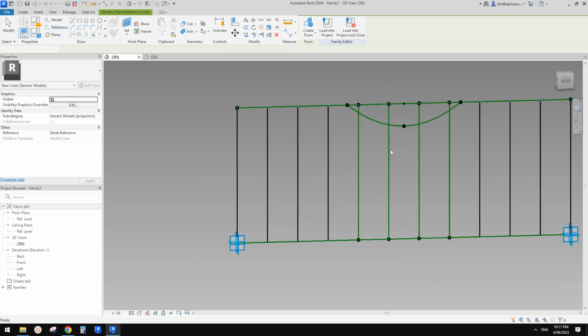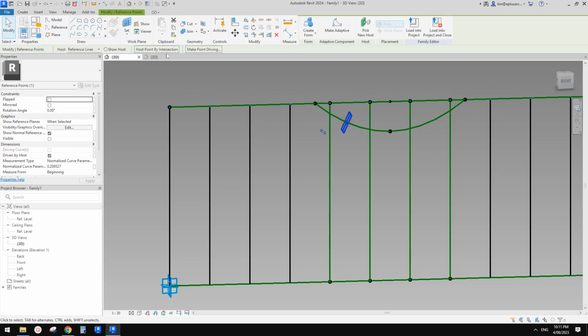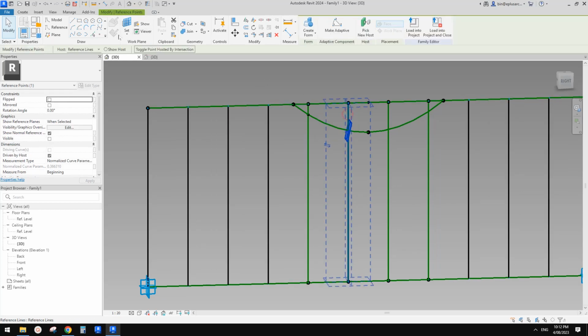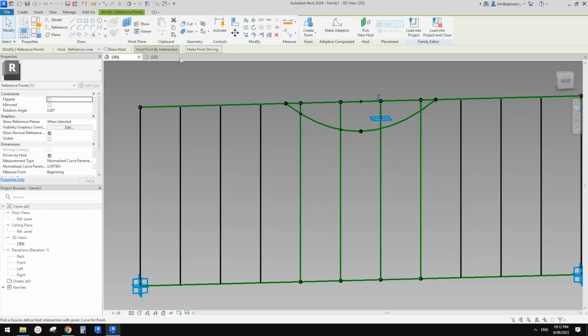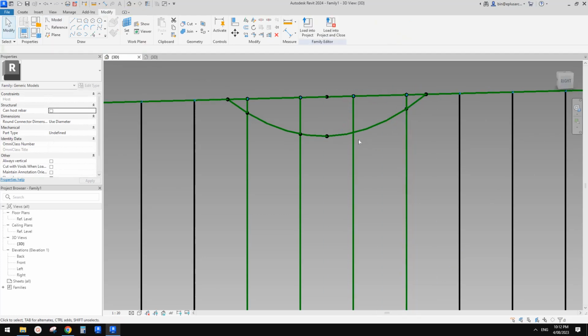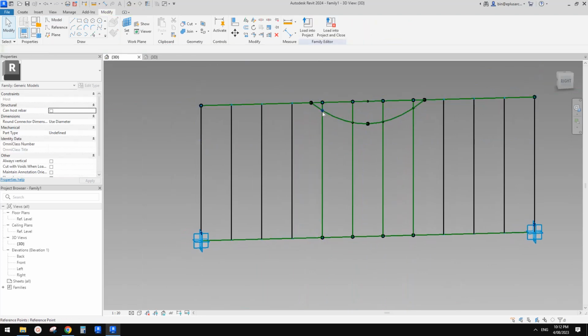So then we can just place a point, and we can just place it here, and then select this point, use host point by intersection, and then pick this. So this will automatically go to that point, and do it the same. We can repeat this, host by intersection, place another point, and host by intersection. Oh, hang on. Yeah, it should be the same. And here, and host by intersection. So maybe I'll just remove this one, and I'll do the same. I'll place onto this, and then intersect with this vertical one. So now we have all these points we need.